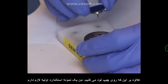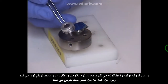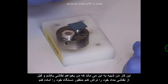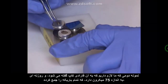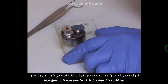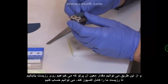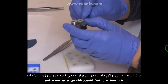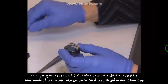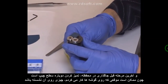In addition to loading the chip, I need 2 standard samples. First, I'll load gold nanoparticle substrate because it has very good contrast and we can use it to optimize the beam before writing. It's kind of like sharpening your pencil before you draw a picture. And the second sample that we need is called the Faraday cup, and it's basically a 75 micron aperture that collects the entire beam so that we can measure the amount of current that's coming through. From that current, we can calculate the dosage that we need to expose the resist fully. And one last step before I load this into the chamber, I want to blow the debris from the surface of the chip that might have landed there from scribing the numbers into the corners.